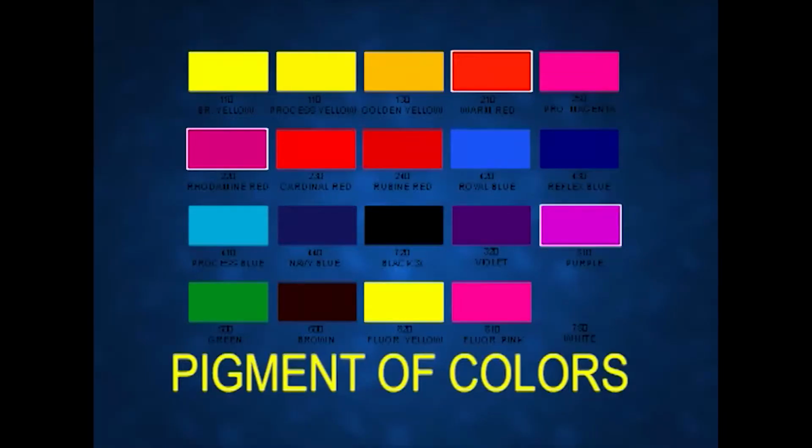Then comes the chemical composition of paint. Now, paint comprises binders, pigments, solvents and some additives. What are binders? The binder is any substance or material that draws or holds other substances to form a cohesive whole. It is a polymeric substance. The binder is mixed with other additives such as drying agents, surfactants, etc. and then dissolved in a solvent.